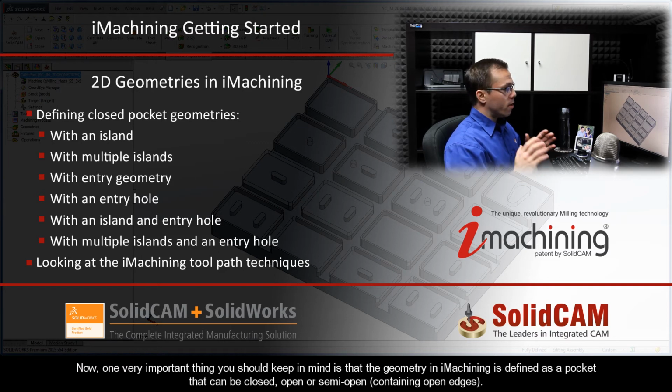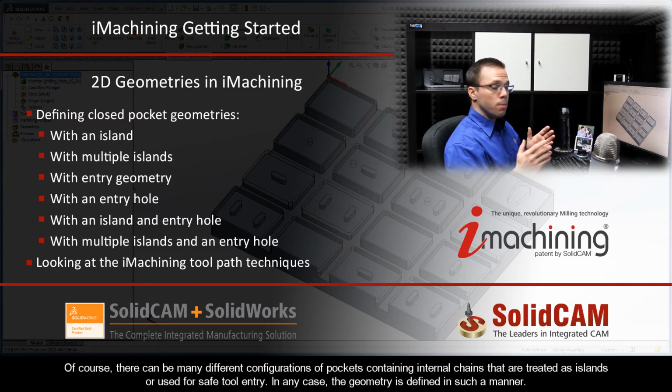Now, one very important thing you should keep in mind is that the geometry in iMachining is defined as a pocket that can be closed, open, or semi-open, meaning containing open edges. Of course, there can be many different configurations of pockets containing internal chains that are treated as islands or used for safe tool entry. In any case, the geometry is defined in such a manner.